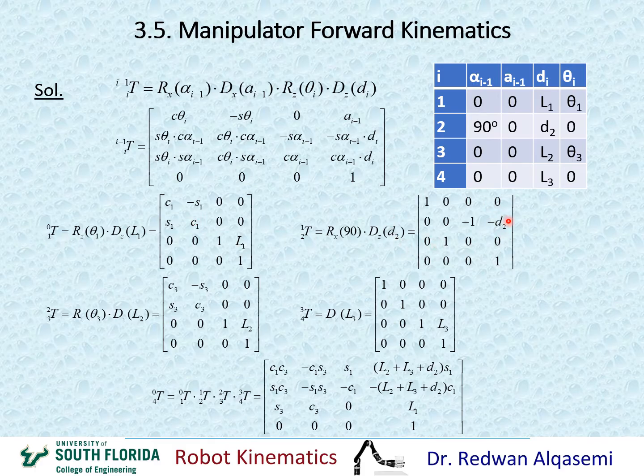And here I have a second joint, which is a prismatic joint. So for the second pair of joint and link, I have one variable here, which is d, in this case d2. And then the third transformation is from the third pair of link and joint, and again, I have one variable, which is theta 3. In this case, this is a revolute joint.